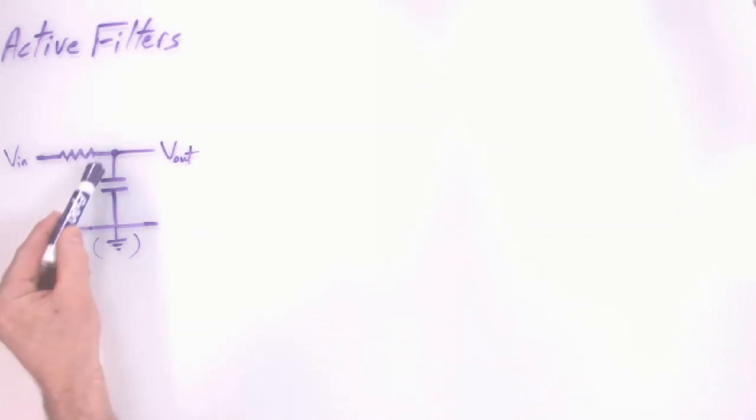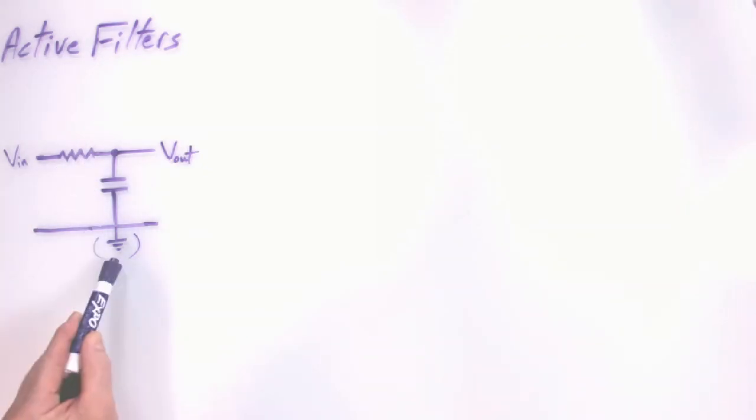Another simple way that you might find useful when you're looking at quickly identifying high pass, low pass, you can look at the capacitor and just recognize that at low frequencies it looks like an open, and at high frequencies, very high frequencies, it starts to get close to a short. And so what that means is high frequencies would be shunted or shorted out down to ground.